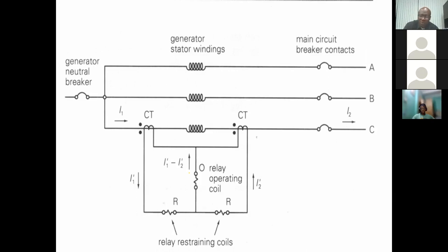And so we will have to go through a process where we try to determine the maximum possible current that can pass through this transformer. And how do we mitigate against that confusion in the differential system? Here we know the differential means that if the current entering is the same current leaving, we're good. We don't have to worry about it. But if there is a difference, then it will energize the operating coil and the relay will operate.